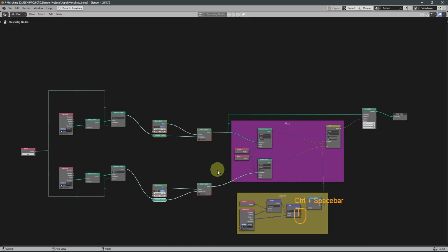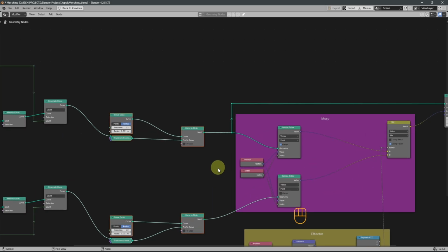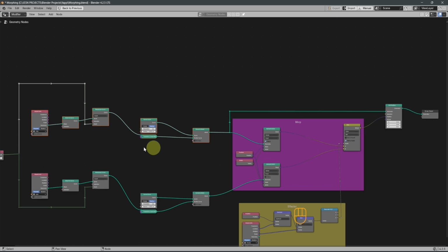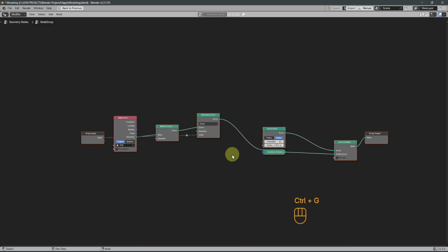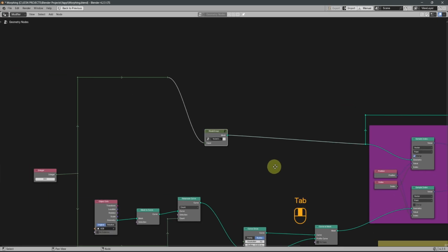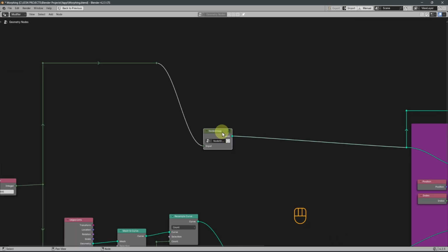So to do that, let me arrange my scene some more. Let's drag from here to here like this, and then press Ctrl G to group them together, and then press Tab to exit. So select this and then rename it. Let's name it plastic can.